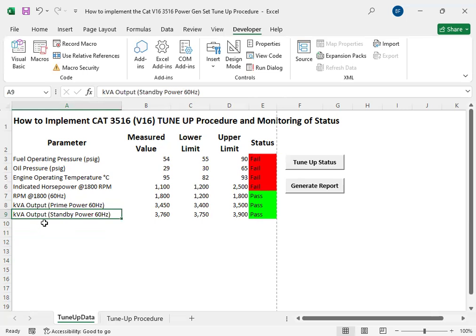If you have an amp probe, you check each cable. There are three cables. This is three phase. So you check each cable. Just like doing the engine test in the dynamometer, you can also test the generator itself outside by doing a brine test. What is a brine test? You have a tank with water and salt, and then you dip the three phase output of the generator with the engine running. Then you'll find out whether the engine will be able to handle the output.